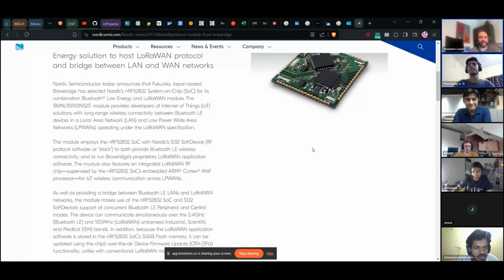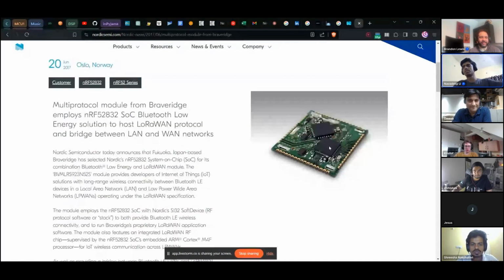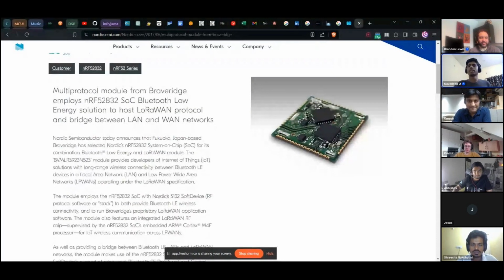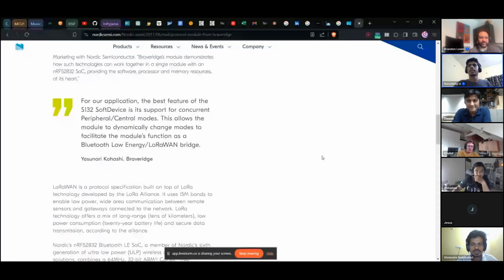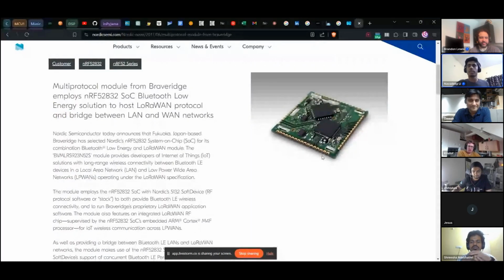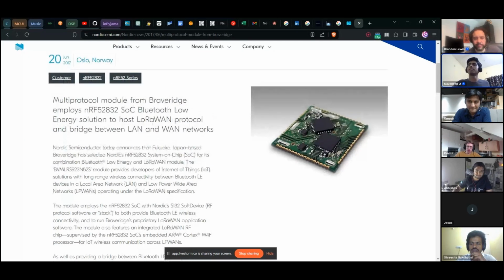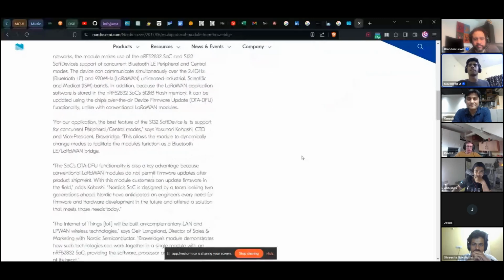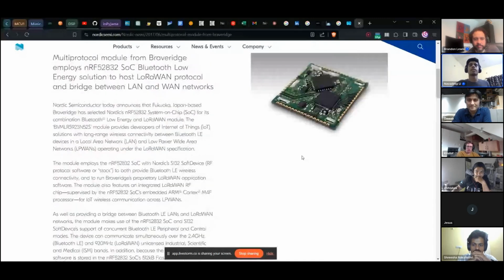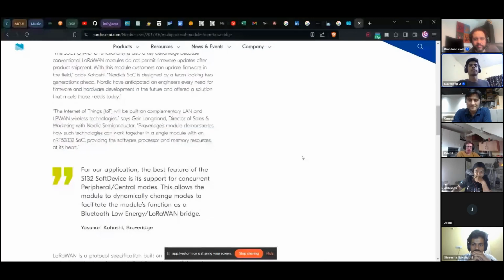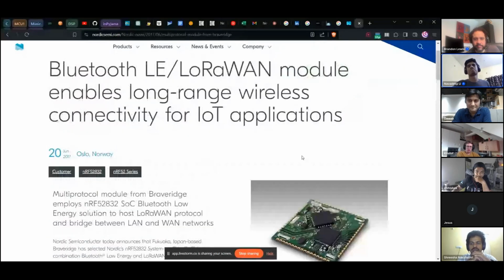Hope that helps. These are classical form factors for those modules. LoRaWAN modules come with this type of carrier card or system on module, where it exposes all the peripherals, and some come with an inbuilt antenna, like a ceramic chip antenna. Some have, I think this most likely has, a coplanar waveguide. So you would have to extend this, put in a matching network and extend it.